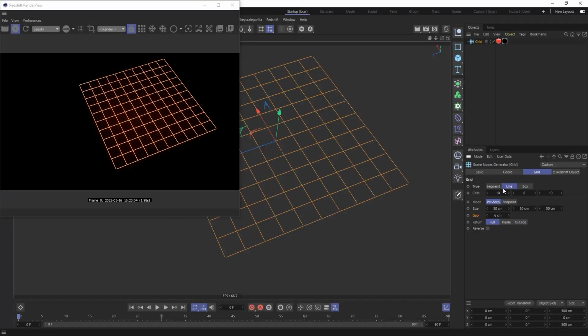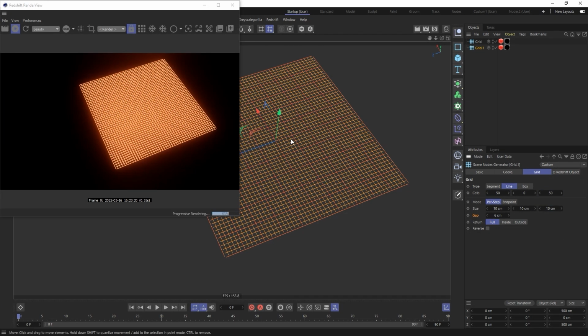And now, let's see, how would I like to do this? Let's make a duplicate. And this one, I'd like there to be way more. Let's make this be divided by 5, which would set it to 10 by 10 by 10, which means this has to jump up times 5 instead of divided by 5. And then you can see I've got 5 times as many grids there. So those are overlaying each other, looking identical, but let's change the way those look.